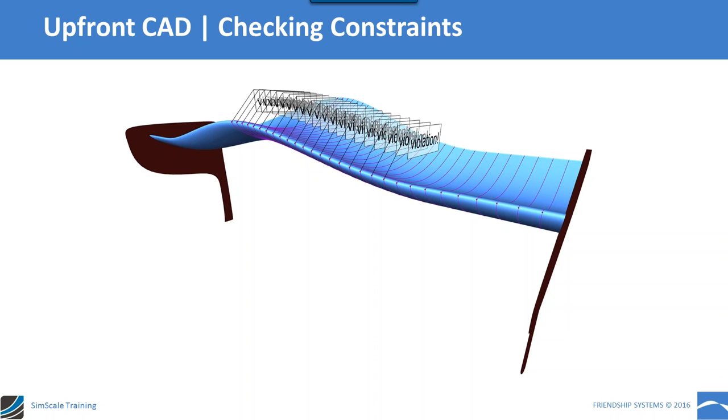For example, you can design a front wing, and at some point if you run your optimization, the chord length is larger than the box, and you will test some models that are not legal. So for this reason, with our software CAESES, you have the possibility of putting constraints.